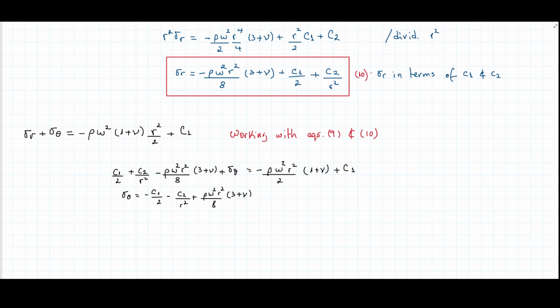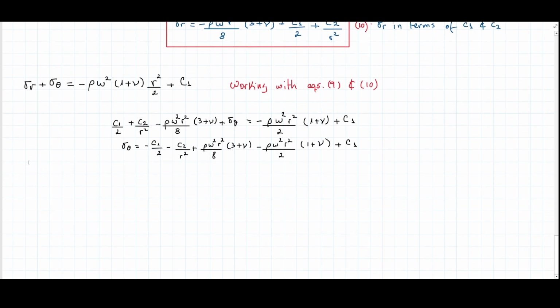And then we are putting everything on this side and then minus this part here. Actually, solving these exercises is way more fun than what we are doing right now. This one here, plus C1. Excellent, excellent. So now what? Well, let's join common terms and let's try to solve for the circumferential stress. And we're going to get the equation that defines the circumferential stress in terms of the radius. And then we need to jump into one interesting concept. So let's keep working with this one.